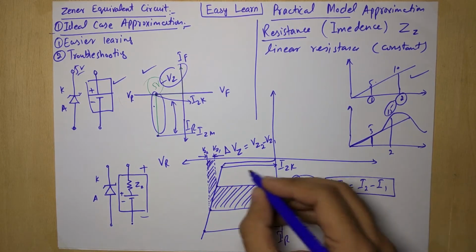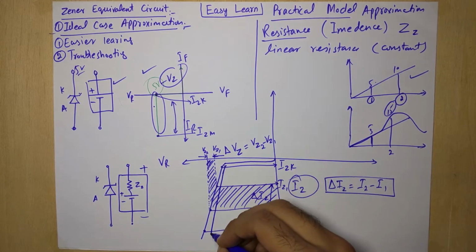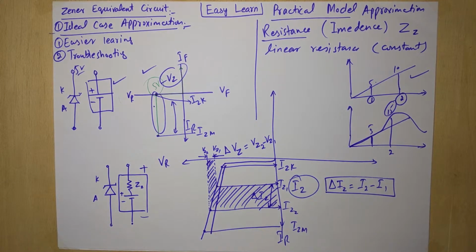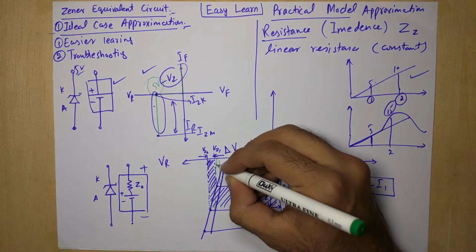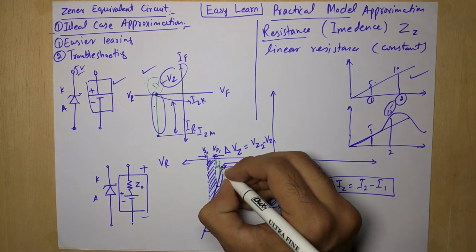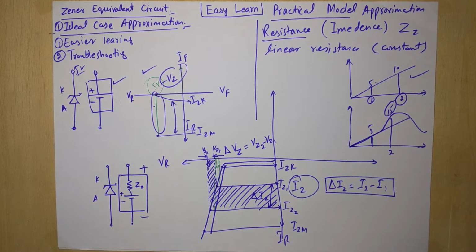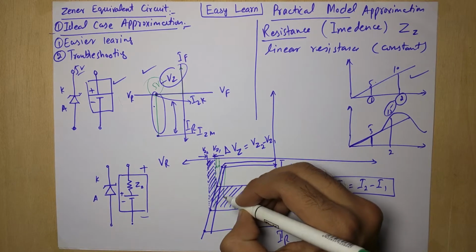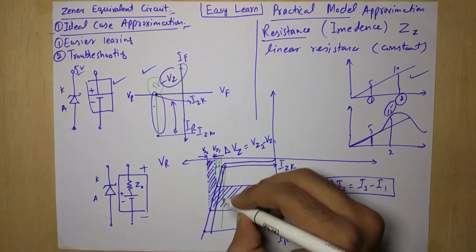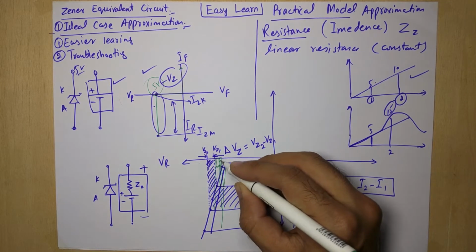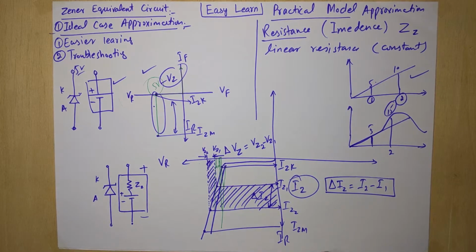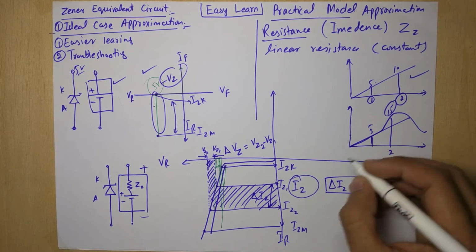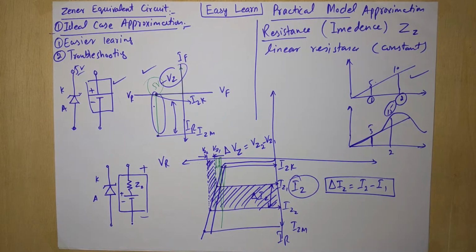If this graph goes more steeper, then the points will look closer together. When the angle is towards 90 degrees, when this curve looks like a straight line on the downside, the regulation is better.